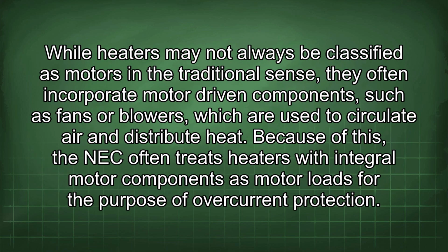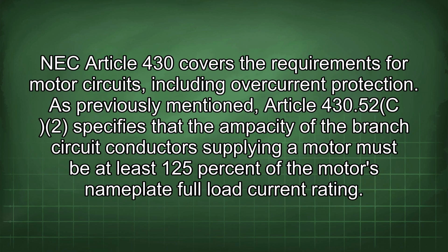While heaters may not always be classified as motors in the traditional sense, they often incorporate motor-driven components, such as fans or blowers, which are used to circulate air and distribute heat. Because of this, the NEC often treats heaters with integral motor components as motor loads for the purpose of overcurrent protection. NEC Article 430 covers the requirements for motor circuits, including overcurrent protection.